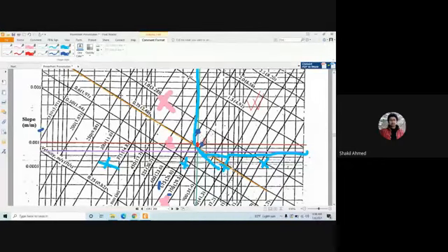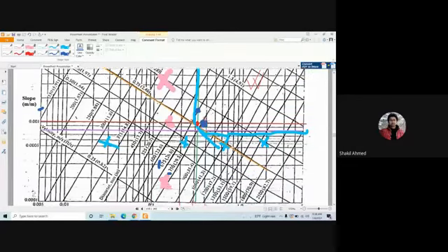Similarly, for this point, you calculate the earthwork excavation cost, and you calculate the cost for 750 millimeter diameter pipe. Then you compare the cost of this and this. The cheaper one will be taken. Clear? Yes, sir. In the exam, you can take either any of these two. You do not need to provide this cost check, but you have to show the partial flow check.